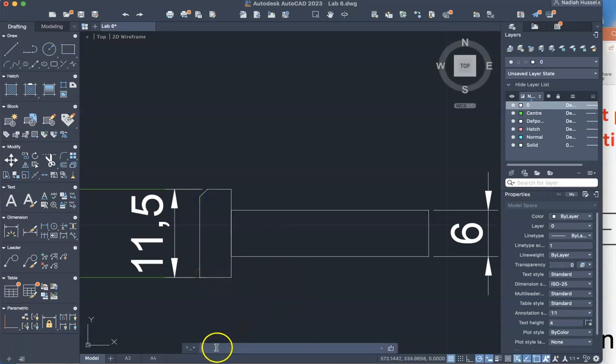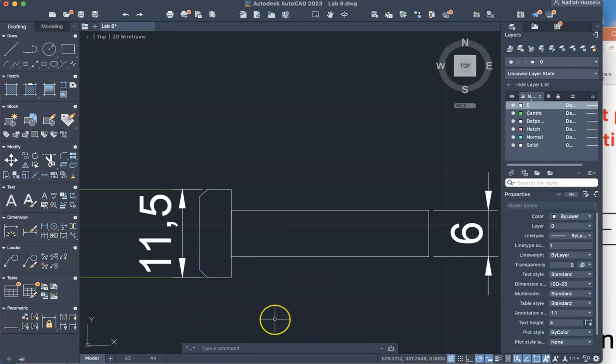And then here you can see the command box is gone. I mean the function is no longer there, but if I click on enter, I will see the chamfer function again. So I'm going to do that again, like so. Okay, for this guy over here, I'm going to change the chamfer distance to be 0.5 by 0.5.